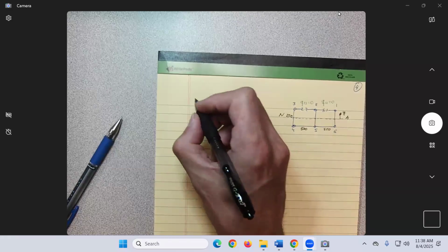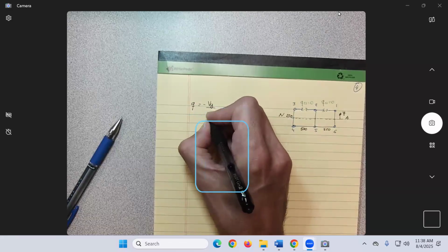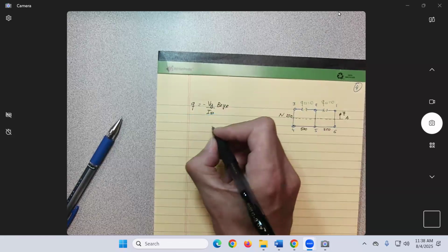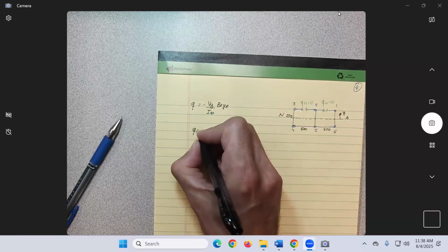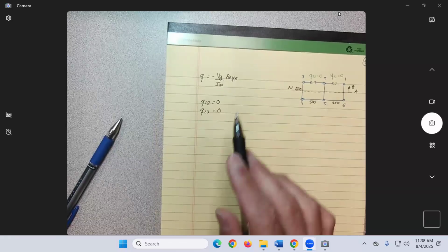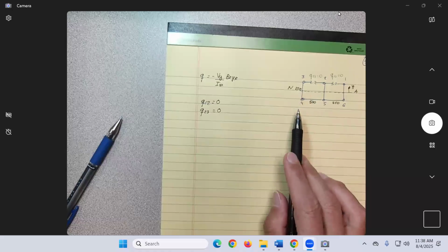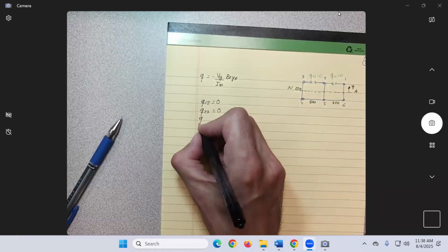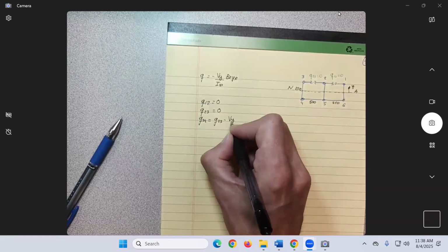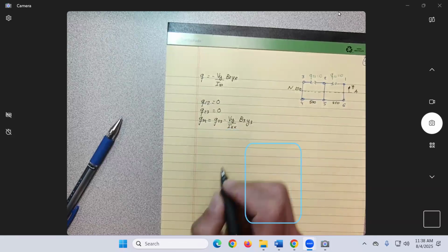We have, so let's recall the equation, which is Q equal minus Vy over Ixx B_r y_r. So we know Q12 equal to 0. Q23 equal to 0. So I go around, okay? First I go around 1, 2, 0, 2, 3, 0. I go to 3, 4. Q34 will be equal to what? Q23 minus Vy over Ixx B3 y3.